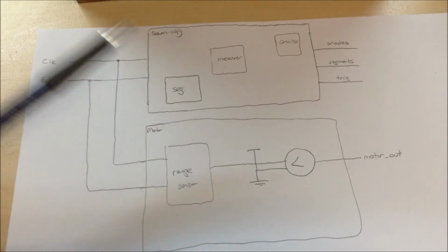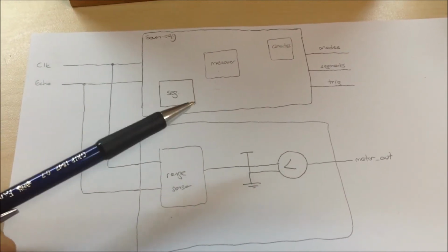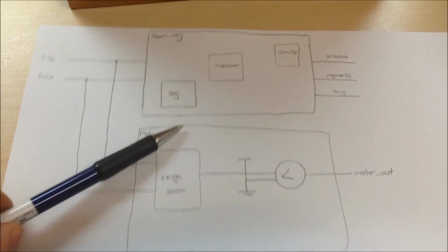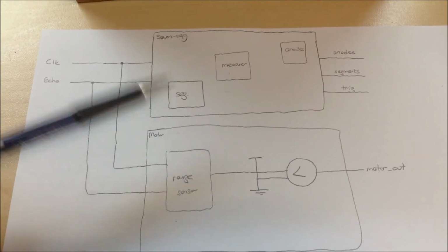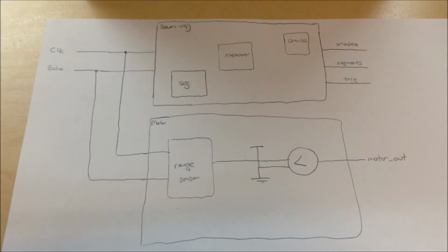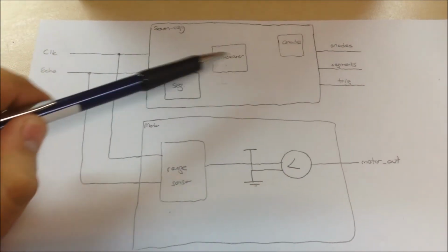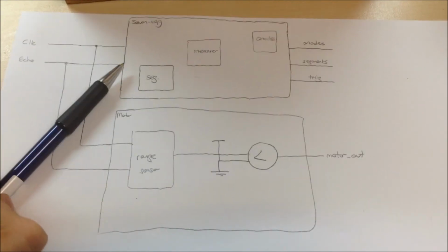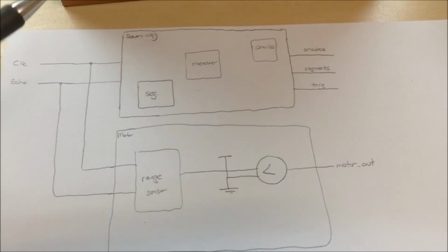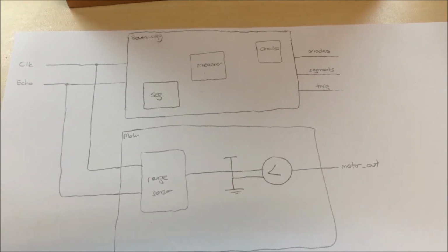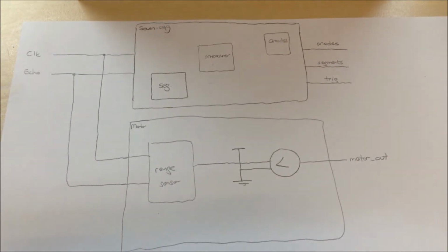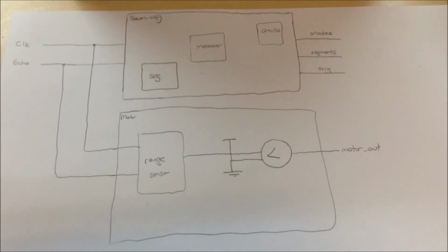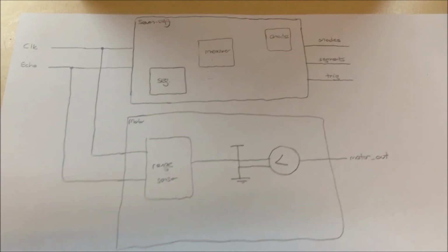As I said, the first module is the 7-segment module. In this module we have a part that looks for the 7-segment display of the distance between the sensor and the object on the platform. Measure is a different module that contains the range sensor module and several if statements that work out the distance from the measured echo time.